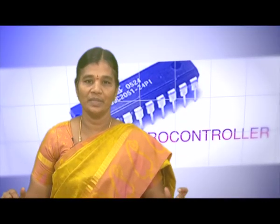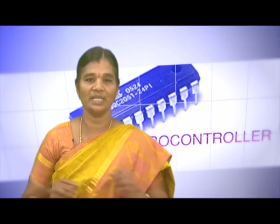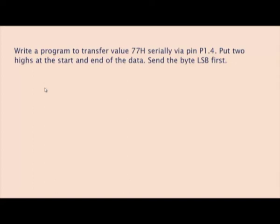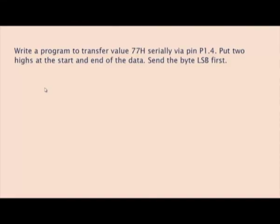Now, we will discuss how to write a program for transmitting a particular number. Suppose I want to transmit the number 77 in serial communication, right. So, how will I convert this 77 into a frame, then transmit it. Now we know how to frame the words, right. So, what you will do, 77 along with the start bit, which is always 0, and the stop bit, which is 1, right. So, this format for 77 means 1, 0, 1, 1, then 0, 1, 1, right. So, this is a start bit, this is a stop bit, then these are the 77.